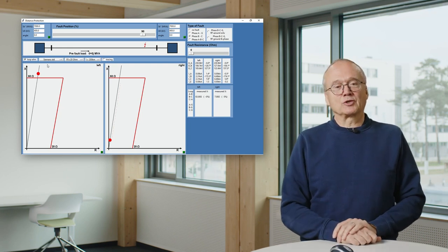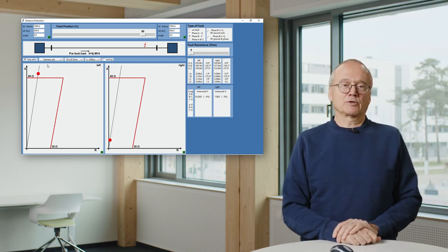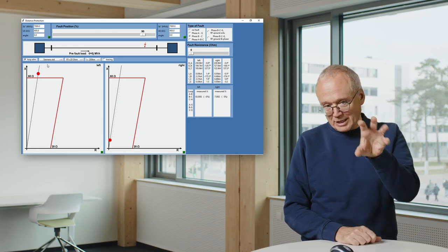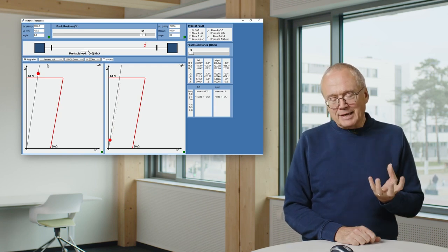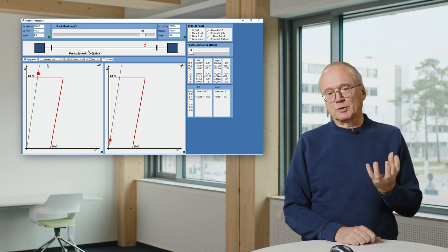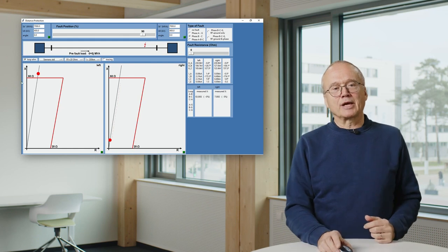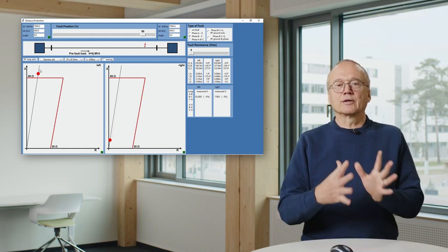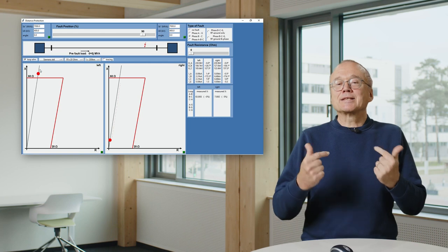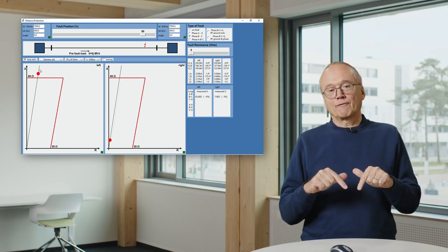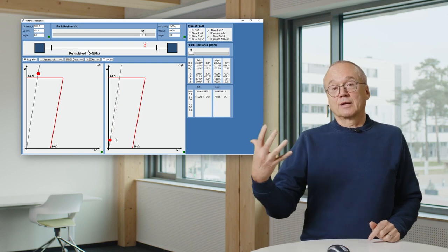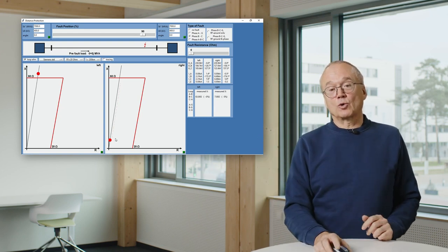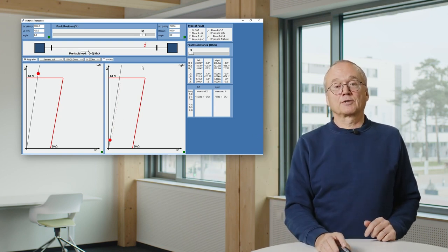And we know Murphy's law, which says that the measurement errors always go into the wrong direction. That means we have to keep in mind that by this setting of 85%, we have the problem that at the end of a line there is a certain part where, at least from one side, the fault is not tripped fast. The other side, in this case the right relay, of course would trip the fault pretty fast.